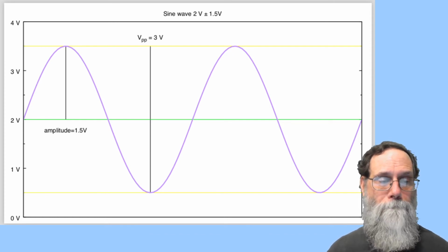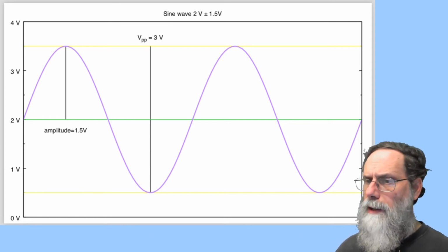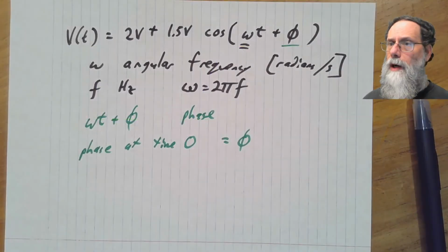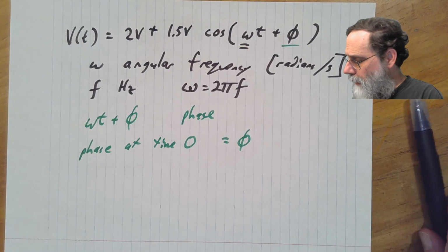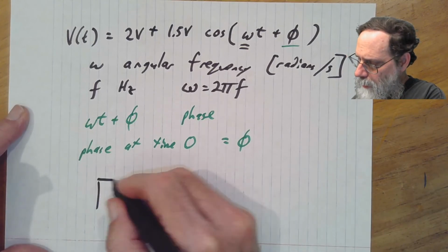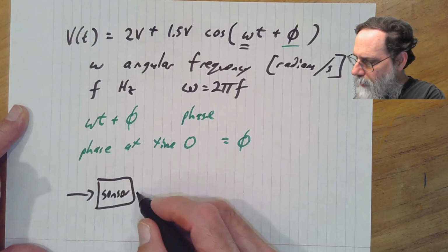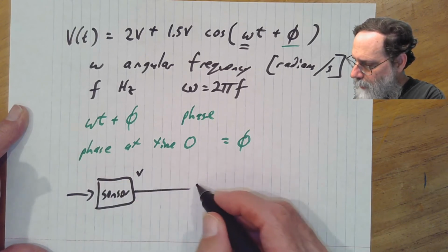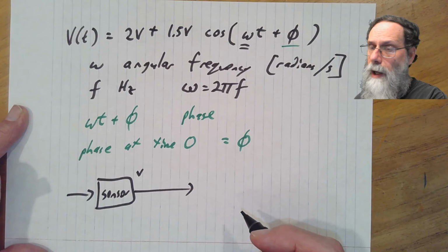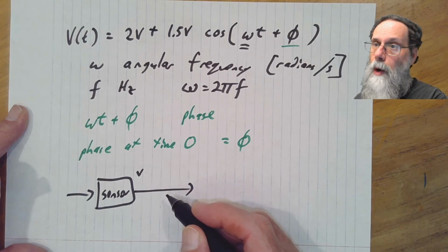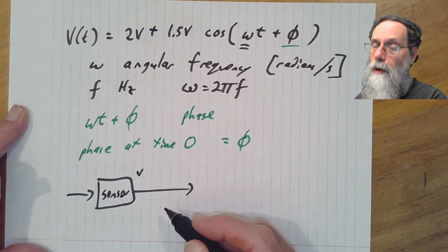Okay, when we're writing a schematic or a block diagram, it's really useful to label our signals. So if I've got a block diagram that says, okay, I've got a sensor here, I've got some sort of real-world input here, some sort of voltage output coming out of it, I'll want to label this line coming out of the block diagram with how big is that voltage signal?